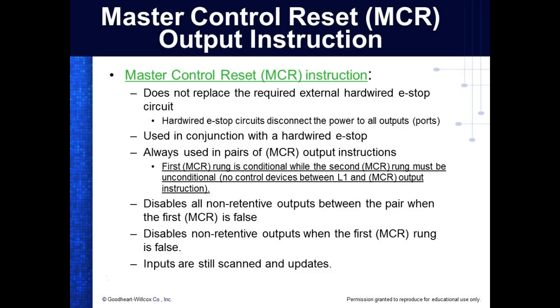This is another instruction that they've added. It's called the master control reset. It does not replace the required external e-stop circuit. So an e-stop circuit has to be hardwired. I can show you all types of regulations. It cannot be done by a computer. It cannot be software. You understand why?